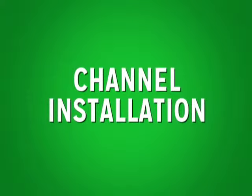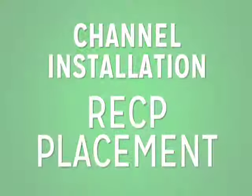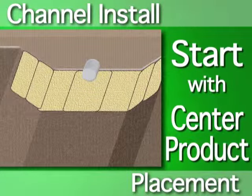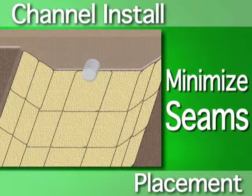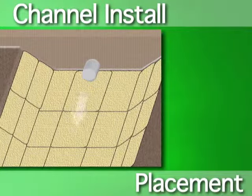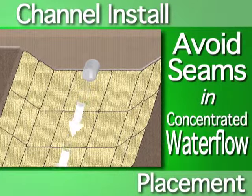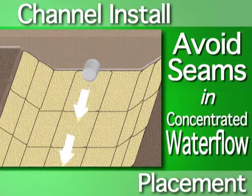Channel installation, RECP placement. When laying product in a channel, always deploy the first roll in the center of the channel bottom, working your way up the sides. Always aim to minimize the number of seams placed in the bottom of the channel. Also, be sure to prevent any seams from going down the center of the channel bottom in areas of concentrated water flow.